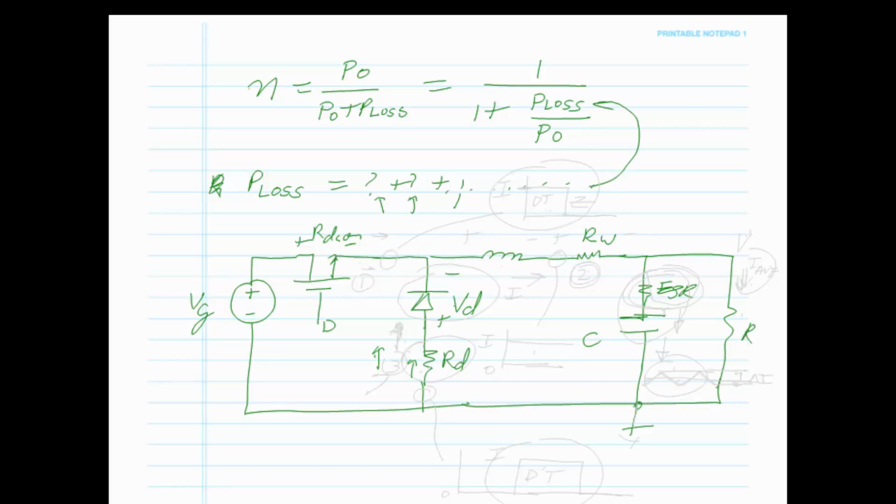So I already established what the polarity was. And this is all plus minus. The current I flows into the inductor, that's the inductor current. Again, what flows through here? That's the average current here. That flows through here. Now, that's different from the average current that flows through there. So I know the current flows through here. All I need to look for is what are the waveforms. If I stuck a current probe here, what would that waveform look like? It would look like this.